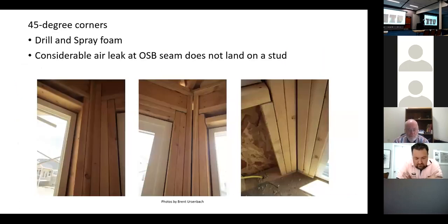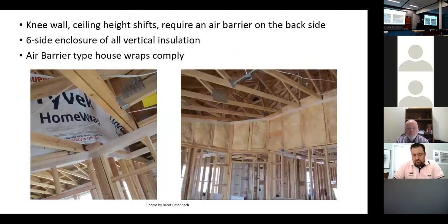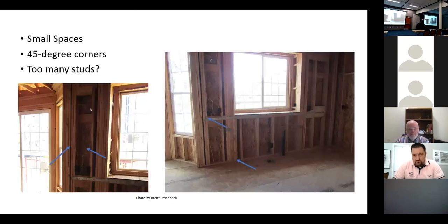Structural engineering on that whole thing could call for 2 trimmers and 2 king studs, that's why you've got so many studs on the side of that. Sure, and I looked when I was there, because that's when I inspected. I looked at the top floor where the point loads were coming down and followed them down, looking for the squash blocks and everything below.